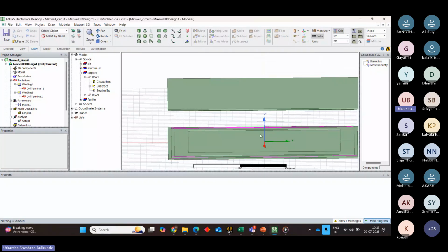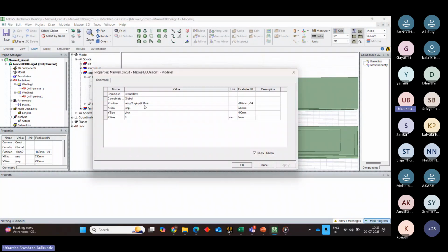So internal diameter, I'll just show you. When you see this, I have parameterized every dimension, right? So X in P is the internal dimension of the primary rectangular coil in X direction. Similarly, Y in P means the internal dimension of your primary rectangular coil in Y direction.